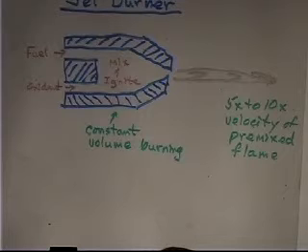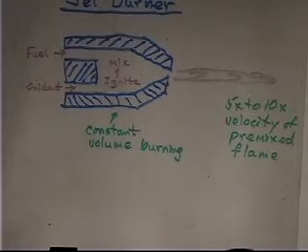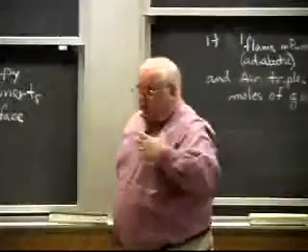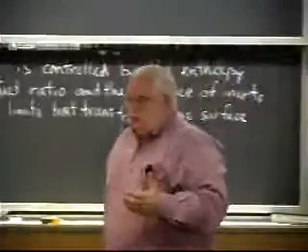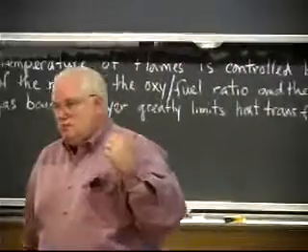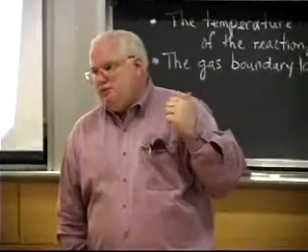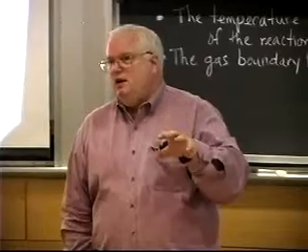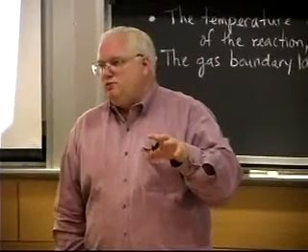You can heat the whole bulk. You can melt aluminum because if I got a temperature here of 1832 by burning in air, so if I put aluminum inside a typical premixed flame, at stoichiometric ratio, I'm going to melt the aluminum. But it may take a fair amount of time because I'm only putting it in at 10 or 20 watts per square centimeter.